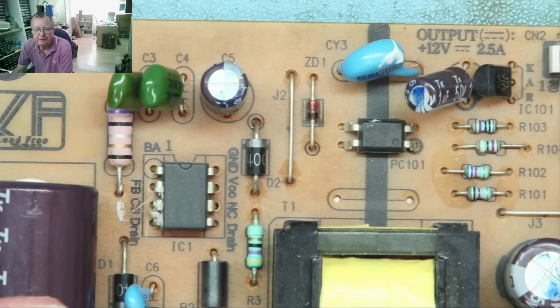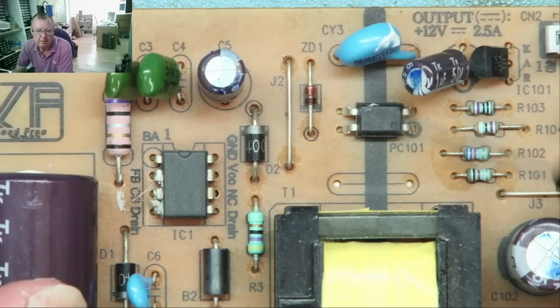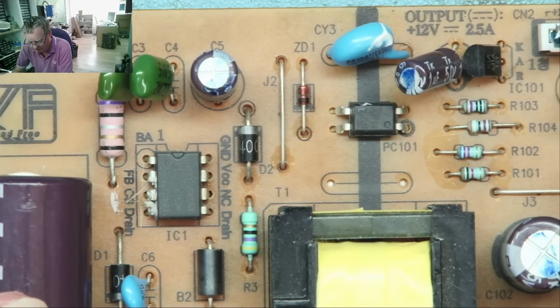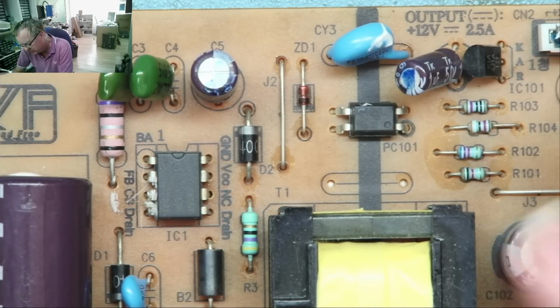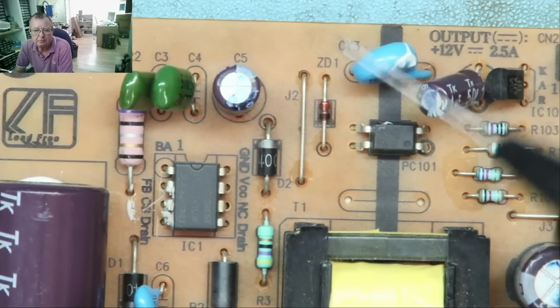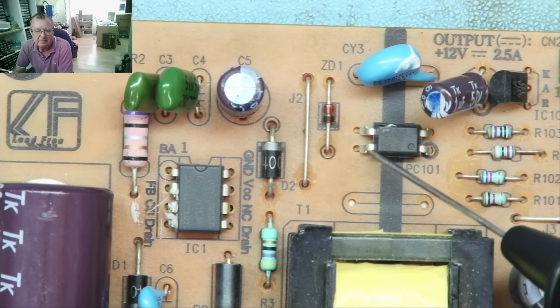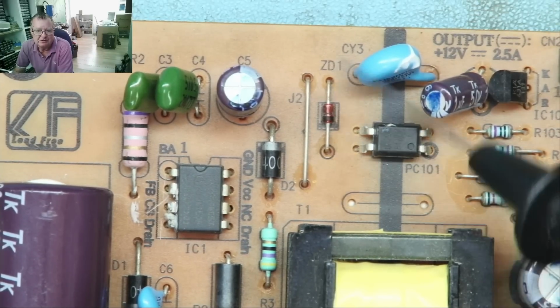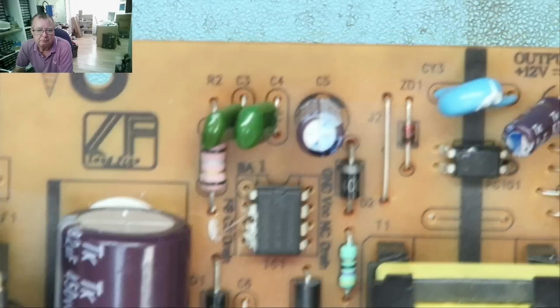To do this, first we need to connect our multimeter in diode mode across the opto-isolator. Now we want to connect it with the negative lead from the meter to ground. And we can also do this in resistance mode as well. Sometimes you have to try one or the other to get a good reading. So normally speaking, on a power supply, one end of the transistor in the opto-isolator, that's on the high voltage side, one of the pins will go to ground.